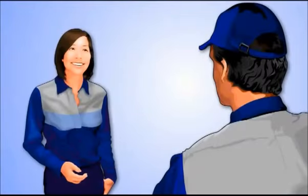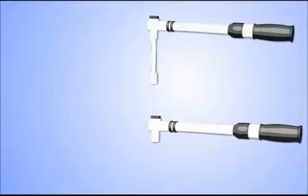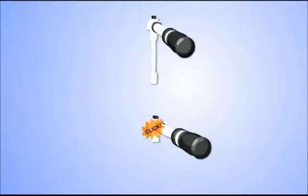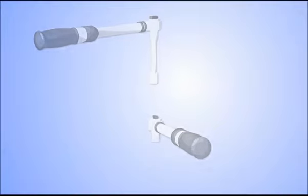When using any tool that attaches to a torque wrench, keep in mind that some attachments will affect the amount of torque applied to the fastener. Straight extensions that extend 90 degrees to the torque wrench will not affect the applied torque. The extension may flex slightly, causing the wrench to turn further than a wrench without an extension, but the torque applied to the fastener will be the same.